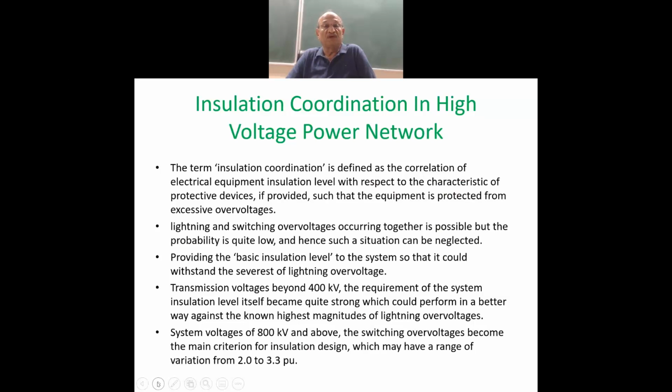So if you had a good system to not let very high transient overvoltage reach the transformer at all, you may get along with a lower level of BIL or SIL, whatever is necessary depending upon the rated voltage of the gadget.